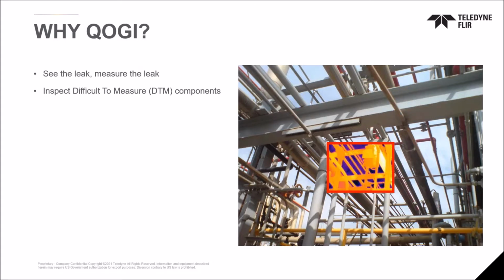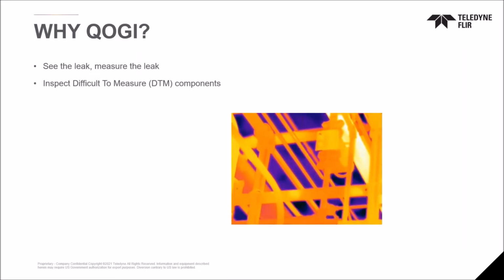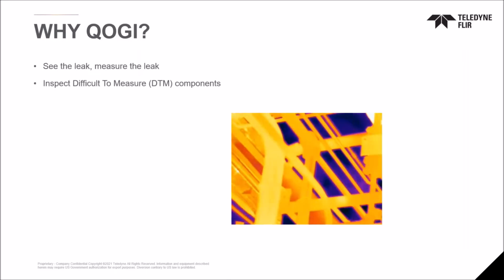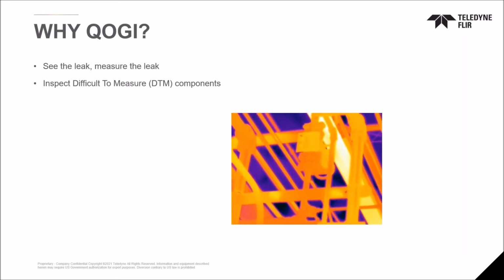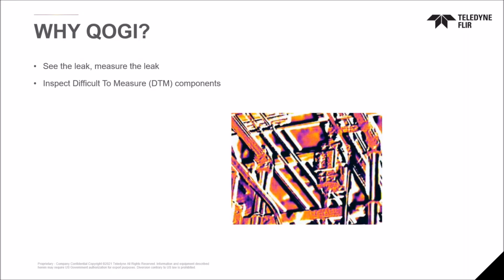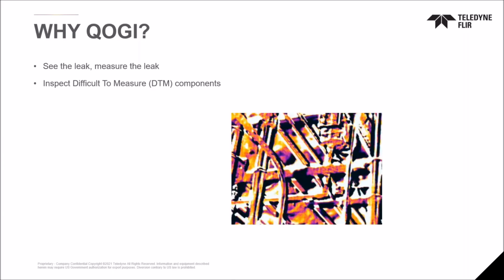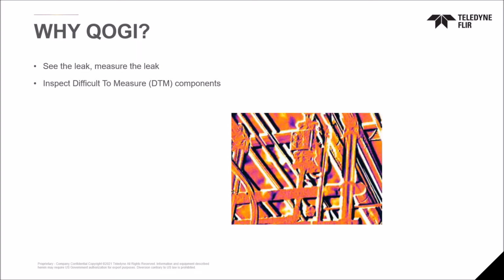Being able to use OGI and QOGI allows you to not only see those emissions, but now you can use the technology within the quantification of optical gas imaging to, at a safe distance and at a distance that cannot be used with other technologies, be able to actually measure those components.